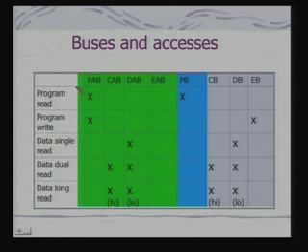What I was interested to show you is how the processor uses the different buses, because it gives you pretty good efficiency in supporting what is called multiple memory accesses. You would like to have multiple data points brought in, multiplied and accumulated, and this whole operation you would like to do in a proper sequence.